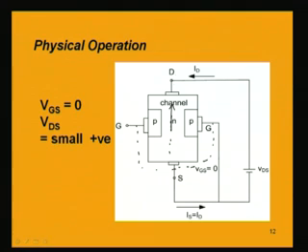The same current will go out from the source terminal and end at the negative terminal of VDS. So, this completes the current path. The drain current is equal to the source current. So, it is clear that even though we are not applying any gate to source voltage, the current will flow from drain to source because of the attractive force due to the VDS on the electrons in the channel.